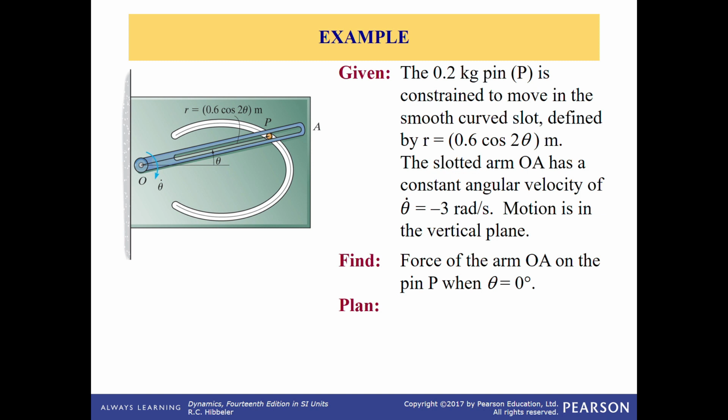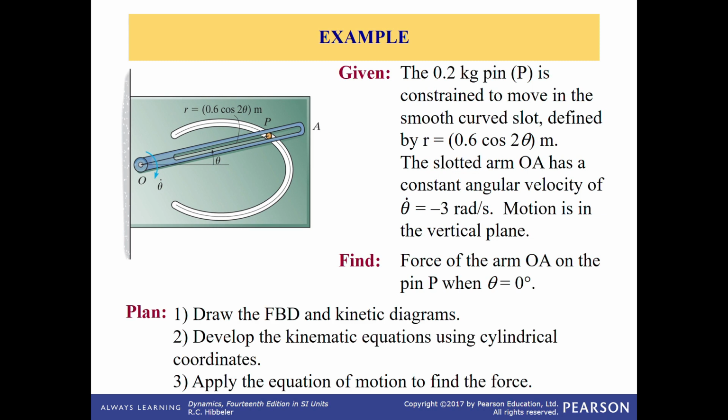What is the plan? First of all, you need to remember that this is the basic in every time you want to solve this kind of question. First, you need to draw the free body diagram and kinetic diagram. Remember that the free body diagram always shows the particle and the forces acting on the particle. Only that. Don't mix up with any other parameter.